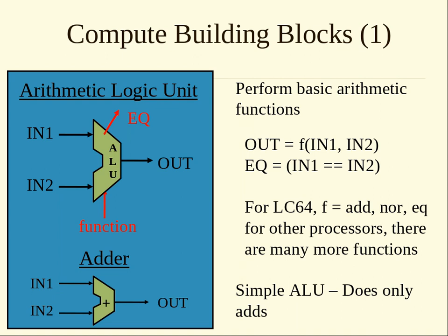And the ALU. Notice you have inputs and you have another wire coming in. This is very similar to a MUX, but instead of selecting which input, you're selecting which function to perform. If the input is add, then it would do an add. If the input was and, then it would do an and, et cetera. So the function is dictating which circuit to activate inside of your ALU. I'll let you all think about how to do that inside of your ALU module, which you will be presenting.